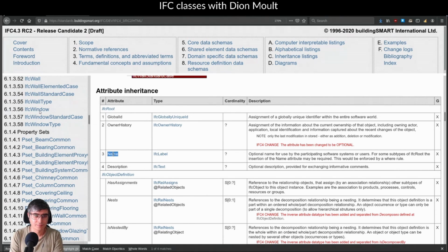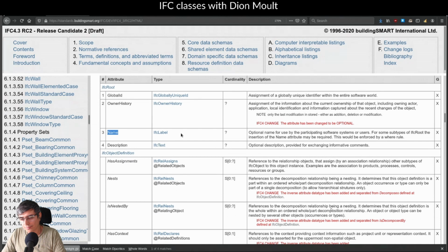I can set a name. You have to skip the first one because it's not a label. It's more complicated. And remember how I mentioned that these more complicated attributes, you can't easily set them in the UI. You have to go to a specific location. I don't have Revit on this machine because this is Linux. But if I did, what I'd show you is that there is a distributed shared parameters file, which you can use to add a parameter to the object. If not, you'd have to type it in manually and make sure you type it in exactly with no typos. And only then can you fill out that value. So it's quite a laborious process and quite error prone.